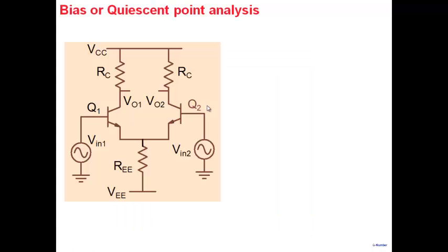Alright, so what we have to do then is a bias point analysis and a small signal analysis of this amplifier. Now, there is one important point that you have to remember in these amplifiers: this is an amplifier which can amplify DC, AC, or whatever it is. So deliberately we will not call it a DC analysis now. DC analysis can be highly misleading because my input signal can also be DC. What we will call it is a bias point analysis.